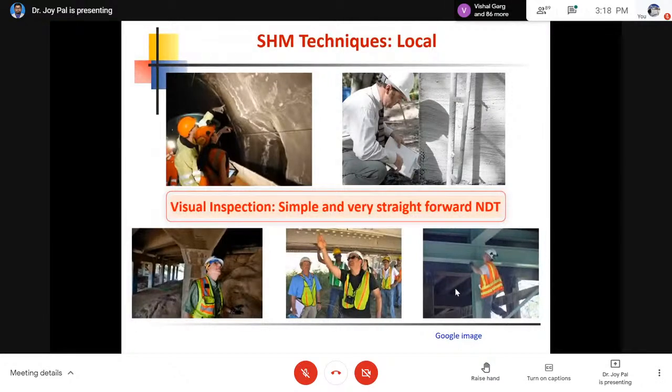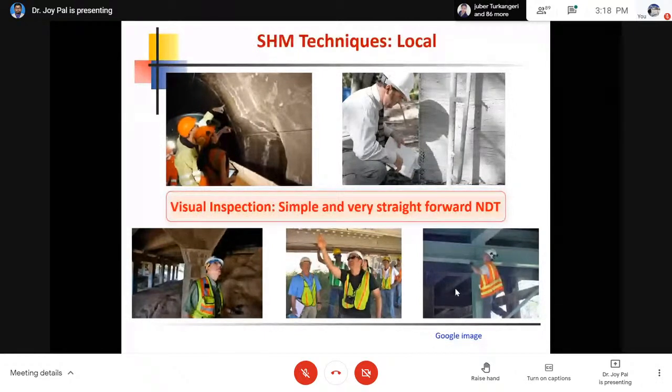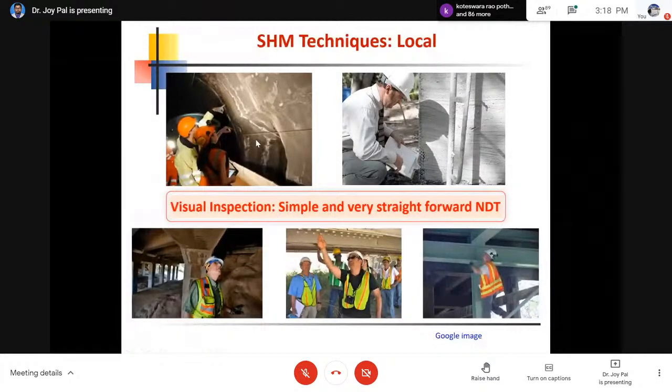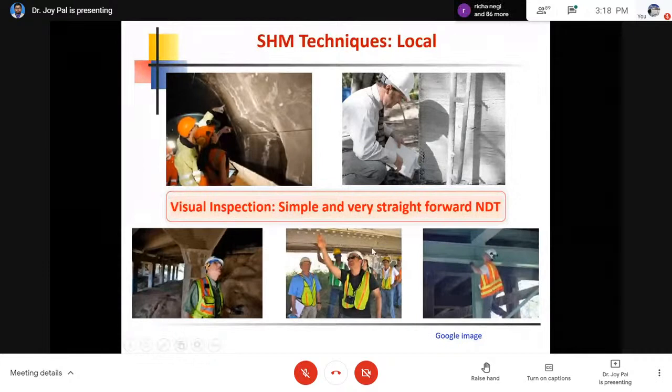He has to go there, check every important point, and then he will conclude. So you can understand how much time and how much experience is required. One important thing I would like to mention here is that the joints of the steel structure, these members, are so heavy that by using hands only you cannot understand whether the bolt is loosened or not, and the joints are the critical location where damage commonly occurs in steel structures. So this is one thing.